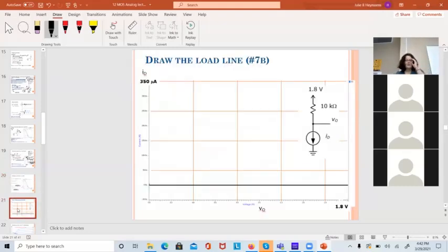Let's talk about the load line a little bit. We won't see this on the homework or anything, thank goodness. This always confused me, but it's fairly simple here. This is ID here, so this is an AC current plus a DC current. Now I can set this thing for ID, but if I have an AC signal coming through here that varies through time, I could end up at some point in my signal instantaneously where the AC equals the negative of the DC.